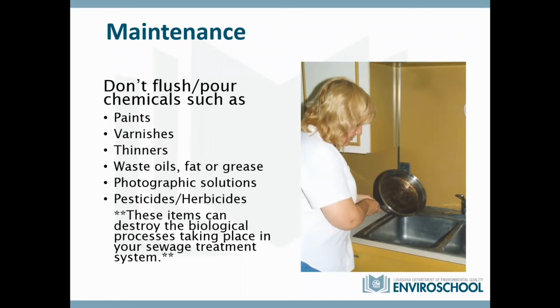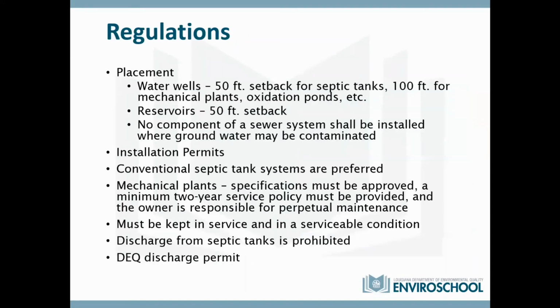And once it congeals, more grease will build up behind it, more stuff builds up behind it, and that will clog the line going into your system. And then you won't be able to flush your toilets and that kind of stuff. So do not pour grease down your sinks. Don't add it to your system. It can get your system off kilter, and the bacteria won't be able to do what it's doing because it's not meant for grease. So this is a bad thing. I just told on myself a little bit too, but I try not to do it myself.